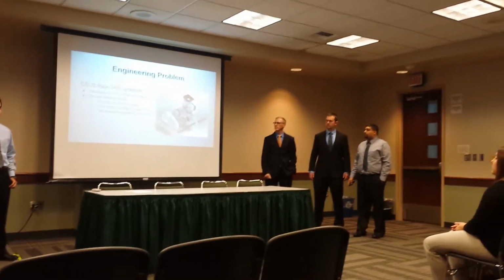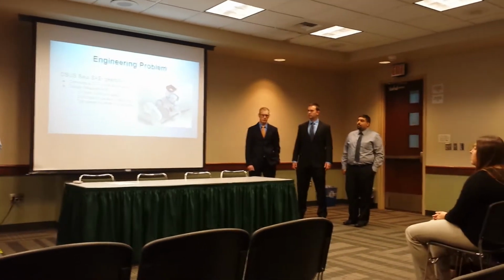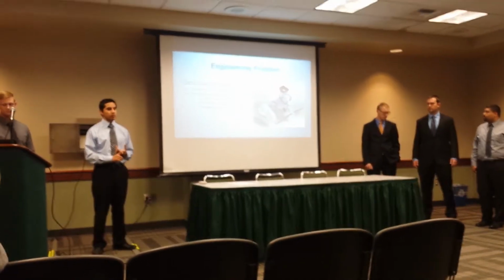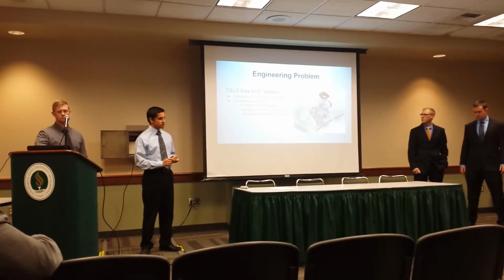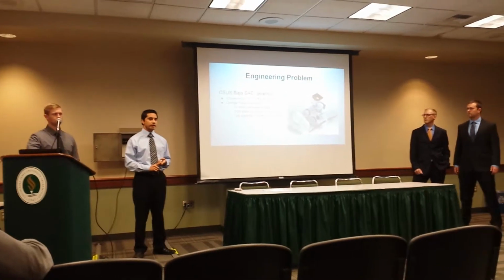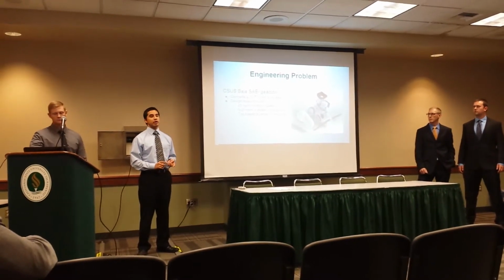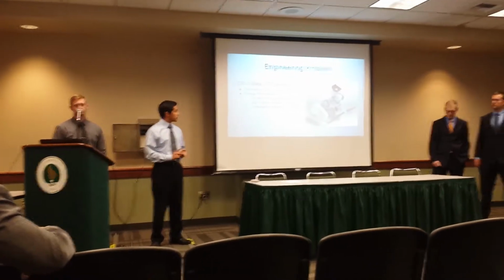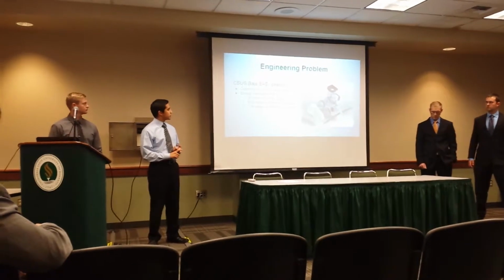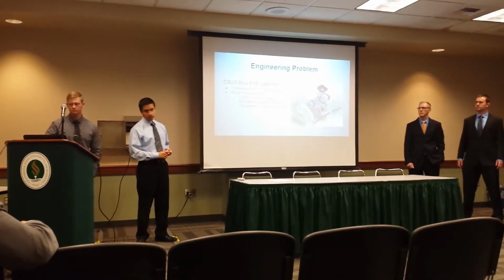However, the current Briggs & Stratton 10 horsepower motor, along with the continuously variable transmission, do not provide the proper torque or angular velocity necessary to meet these design requirements. So, in order to fix this, we have designed a gearbox with a proper gear ratio to meet these requirements. We also give the gearbox the ability to shift into reverse whenever the driver needs it.